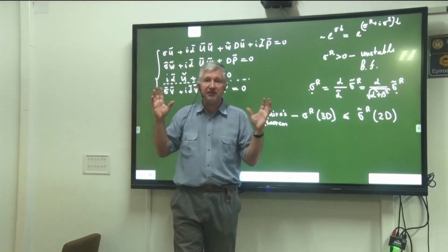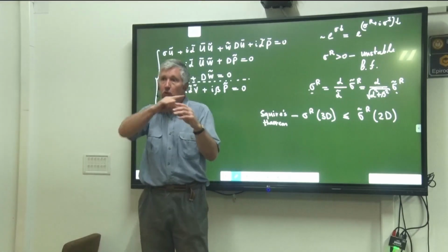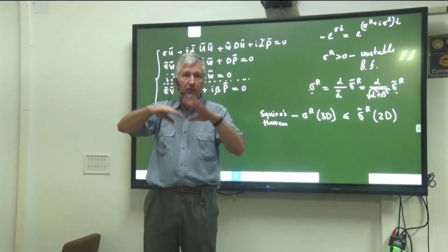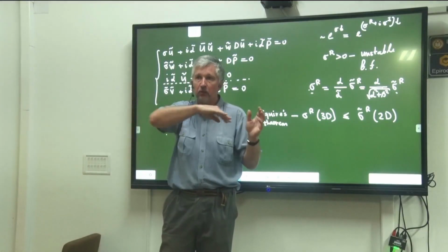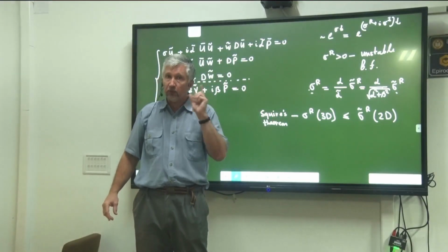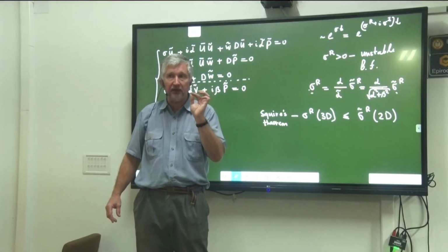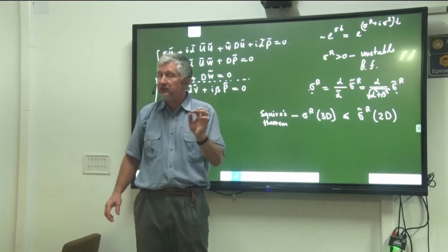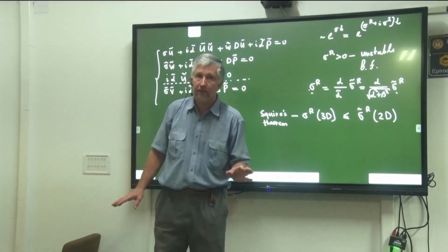If we have a steady state flow, then of course streamlines will be frozen. They will not change. They will be essentially the same as path lines. But for time-dependent flows, path lines and streamlines and streak lines and all other lines are all different.